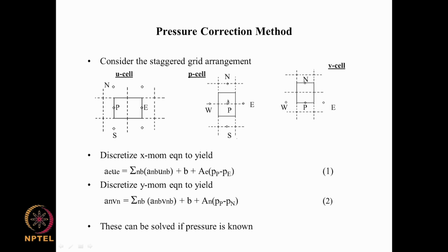Similarly, north face and south face are displaced in the vertical direction by half a grid distance in the positive y direction, negative y direction. So, if this is I comma j, this is I plus half j and this is I minus half j. Similarly, the north face point is I j plus half and this is I j minus half. So, this is our control volume.